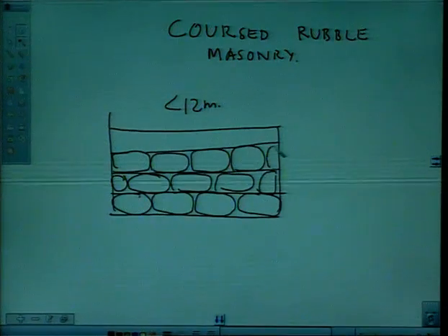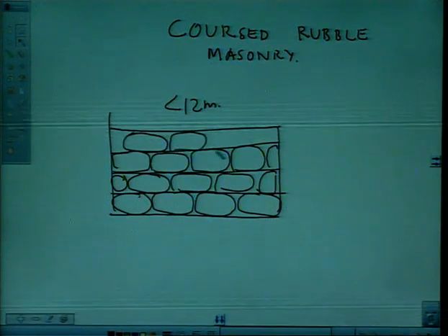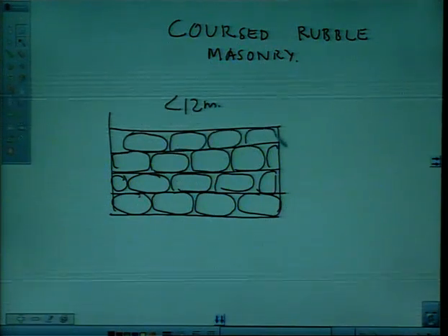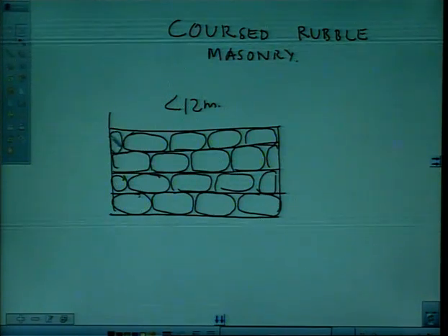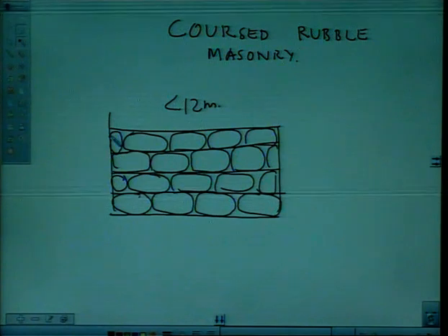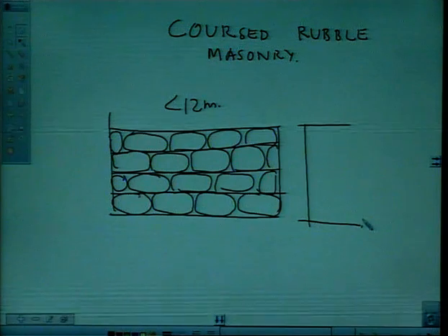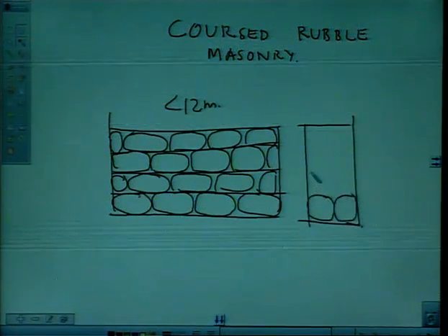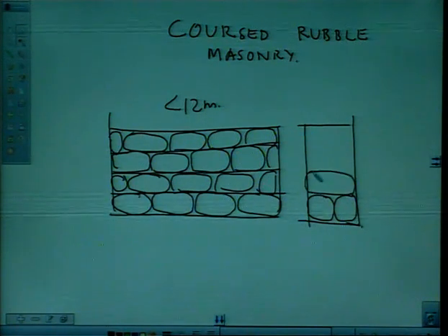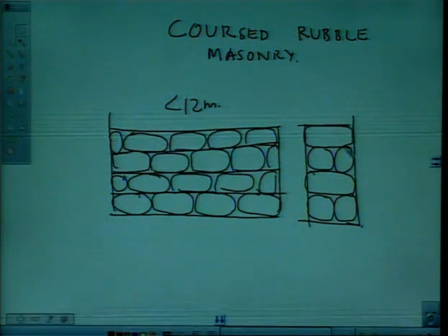Placed in between, so that it won't affect in the earthquake zone. Mostly hilly areas are prone to earthquakes, so don't be mistaken if you are not using mortar. So, mortar should be used frequently. If you see the section, it should look like this one. Through stones are placed after every layer, so that there is better bonding of the wall.